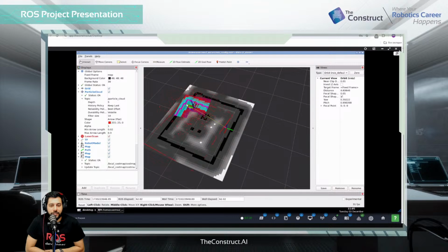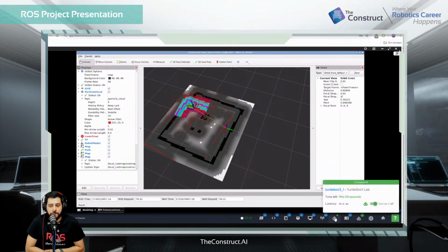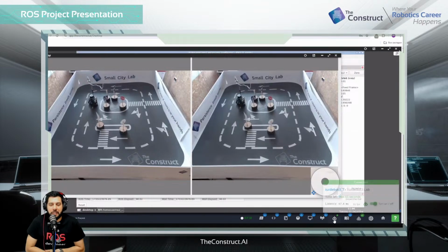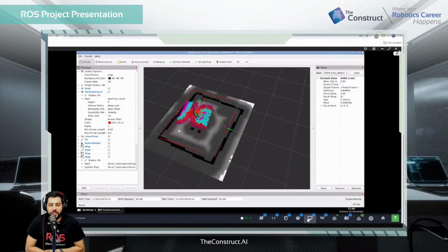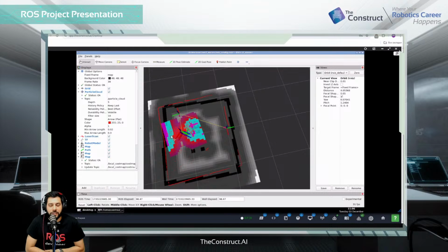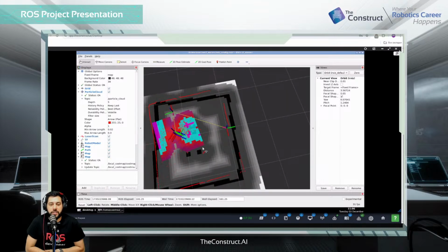When the robot moves, it will find its position more precisely. So we can demonstrate it by moving it manually. I think actually twisting it is the fastest way for AMCL to find it. Oh, that should be enough. Yeah, now it knows its position more precisely. And what are those brighter blue things?